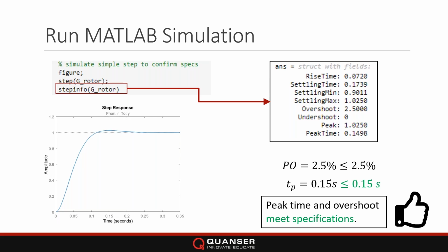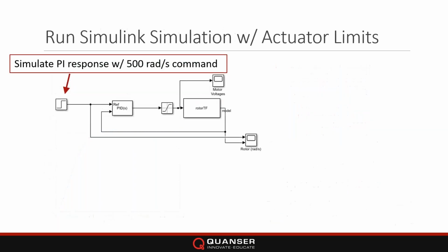However, if you look at the step response, it's giving a reference of 1. That's 1 rad per second. That's minuscule. If you remember when we were doing the model validation experiment, that rotor speed was going about 540 rads per second, almost, right? And so when we're applying a 24-volt signal, which we need to do in order to get a good response from our pitch, you're looking at a much higher set point. So that's what we need to do, right?